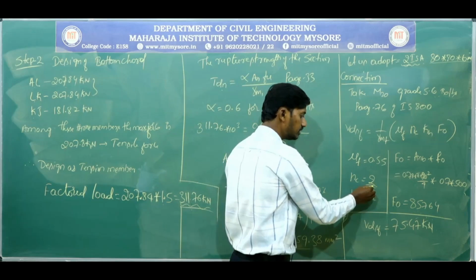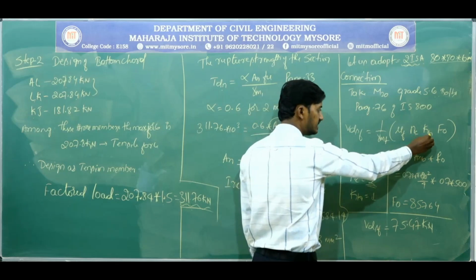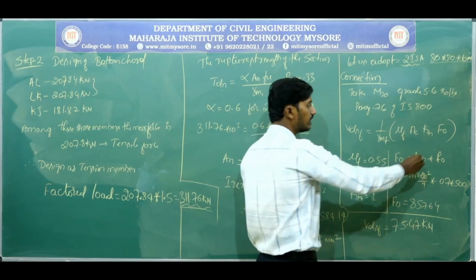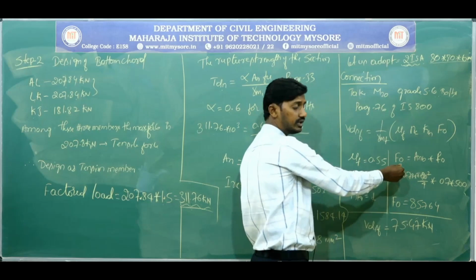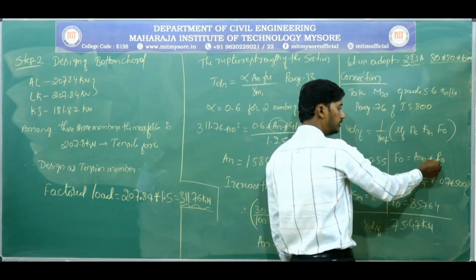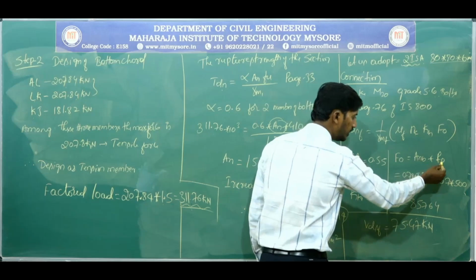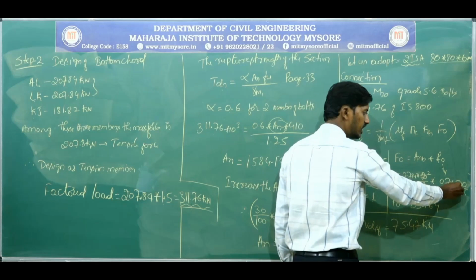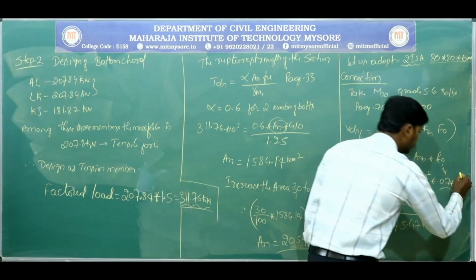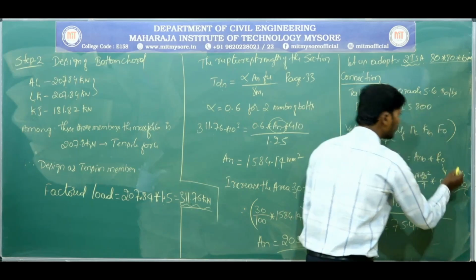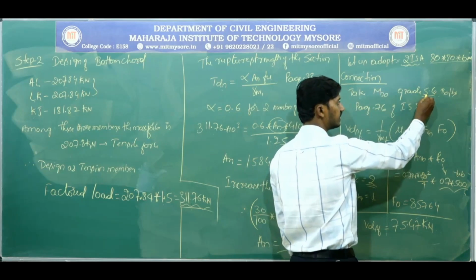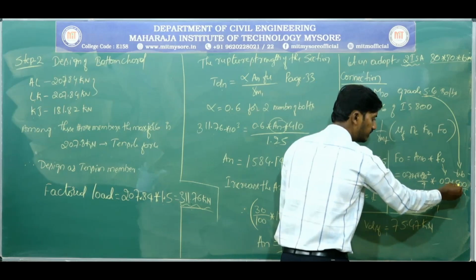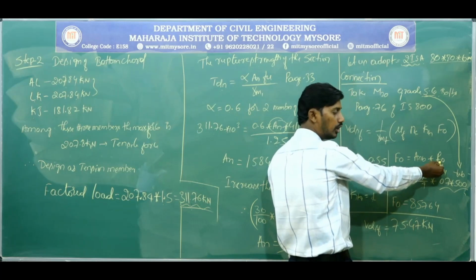There will be two shear planes. And next is Kh, that is available in the code book itself, that is 1. And F naught you need to find out. F naught is nothing but An and b into small f naught. Small f naught is nothing but 0.7 times the ultimate strength of the bolt. This is nothing but FUB. As we have assumed 5.6 grade, FUB will be 500. So 0.7 times 500 will give us F naught.